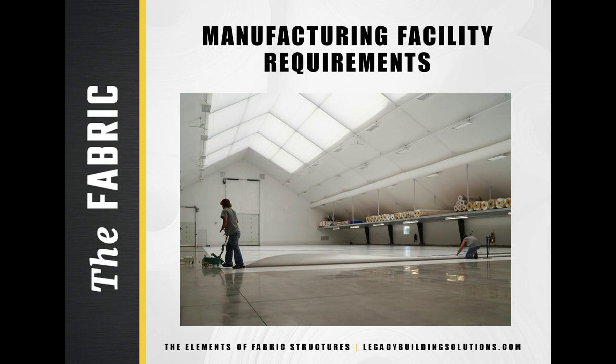Where the fabric panels are manufactured is nearly as important as how. Fabric panels will perform best if the manufacturing facility is kept with proper temperature and humidity parameters to ensure the optimal weld strength, as well as proper panel sizing. Each panel should also be labeled with the location on the building before it is shipped. This will not only save a significant amount of time and confusion on the job site, it will help ensure that the panels are installed correctly.